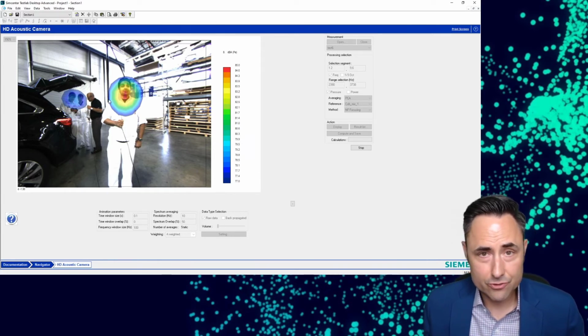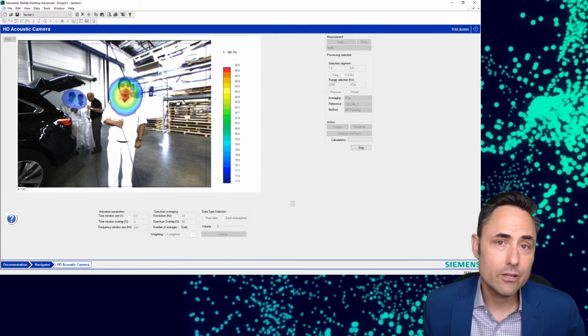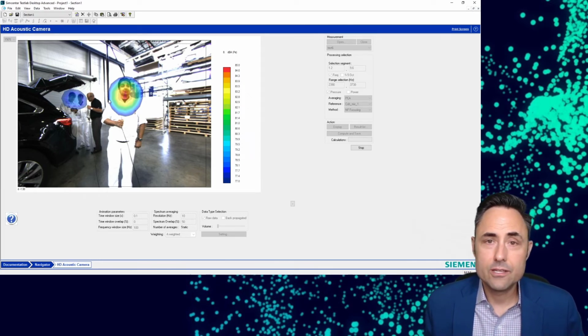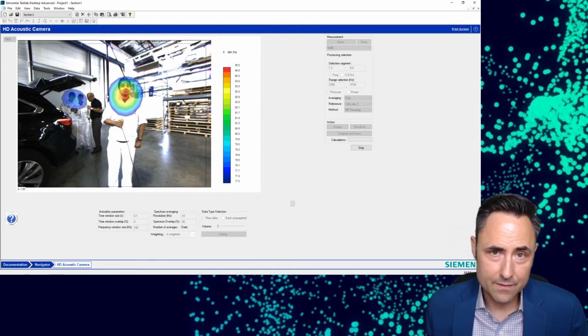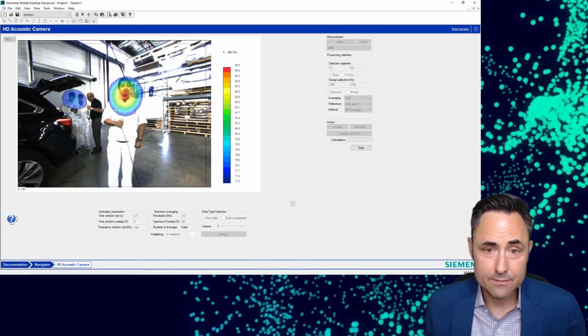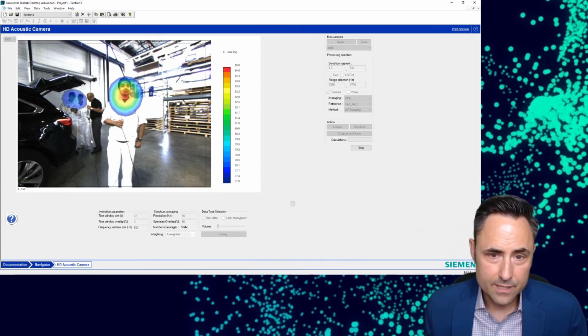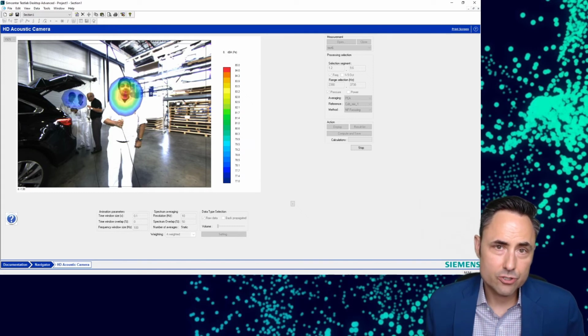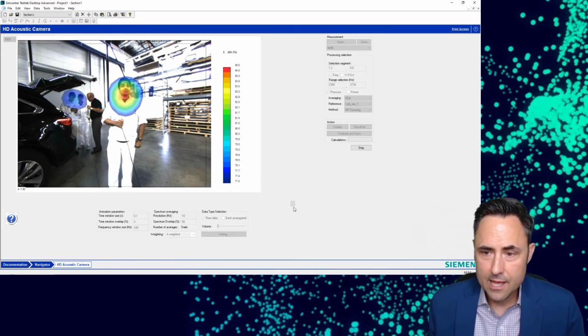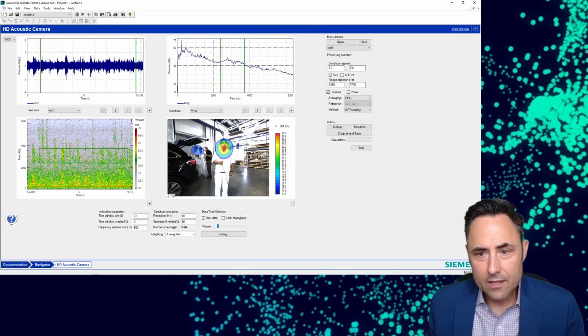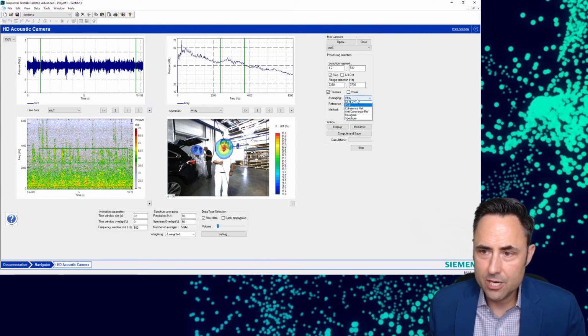Well, by adding an extra transducer or two, I can now intelligently process this data and separate these two sources making the same sound or frequency content. So you notice this guy's holding this cable. He's got a microphone. This guy's got another microphone. And so these are transducers I'm adding to my acoustic array. All right. So I measure with all my microphones in my array plus these two channels. And what I can do is see how much these guys are responsible for and how much this guy is responsible for by changing my averaging to something called coherence referencing.